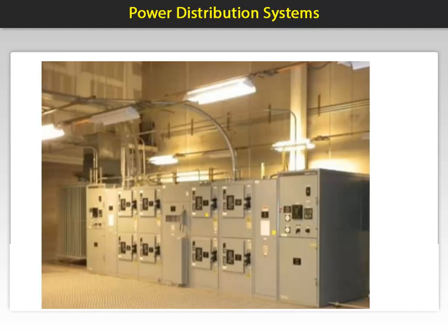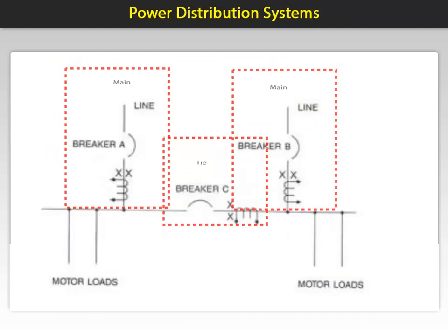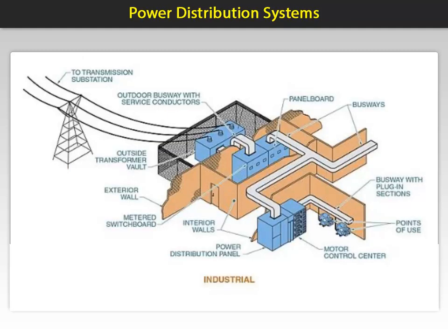Here is what it would look like on a single line diagram. Usually, there is an interlock system used when the tie breaker is closed. Back to our original image. From that point power travels to distribution panels, and/or motor control centers throughout the plant. It would also supply power for motor control centers, transformers, safety switches and enclosed breakers. Even down to supplying power for office lighting and power receptacles.